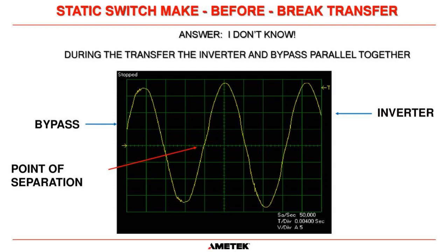Now, when we do testing at the factory here, or when our field engineers come out to your plant and work on the machine, we set up our oscilloscope and we do transfers as part of our PM process. And what we do is we use a current clamp as the trigger on the oscilloscope to monitor if we're transferring to bypass when bypass current is detected. And that's how we trigger the scope to capture the waveforms then. Okay. But all we know is we show the trigger on the scope to know where we told it to go, and then we show the waveform, the actual transfer then. Okay. So if you get one of our PM reports, you'll see the waveforms that we capture as part of every PM and startup.